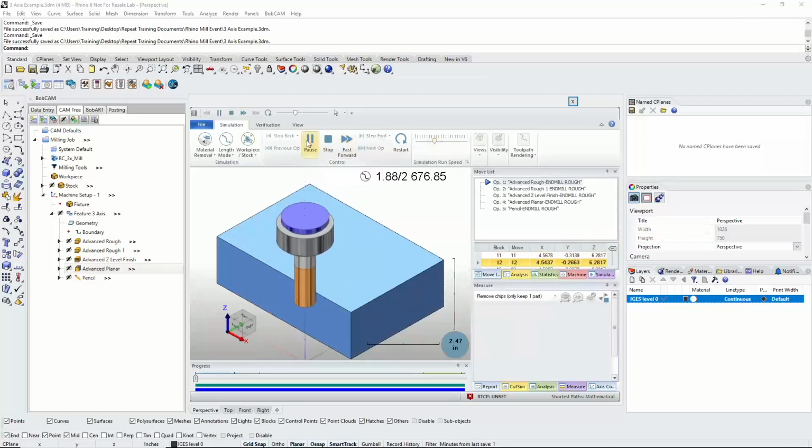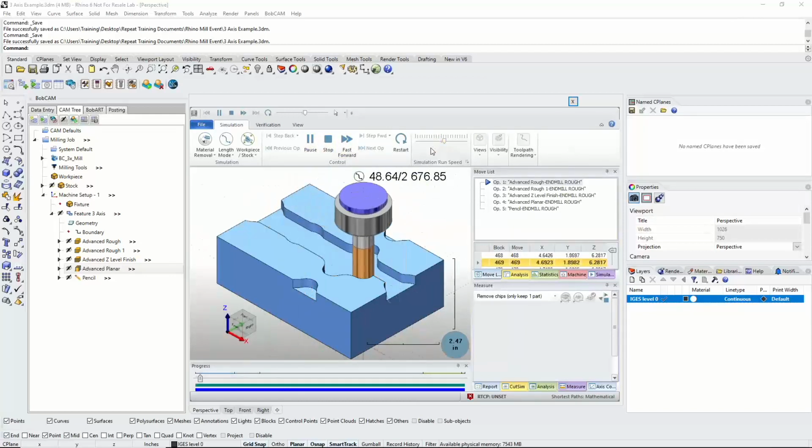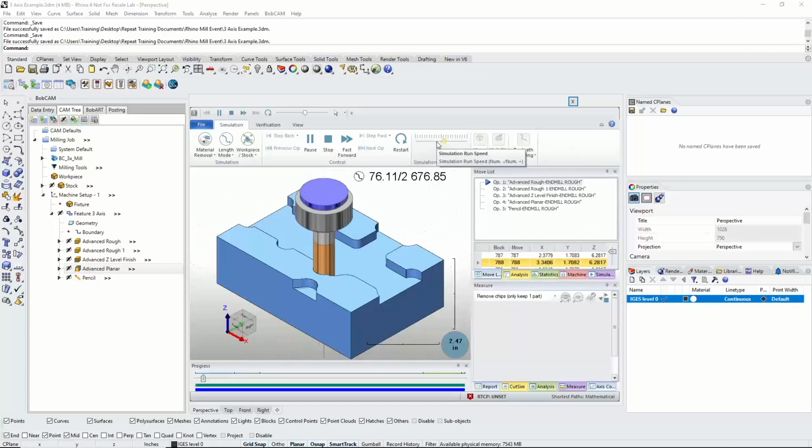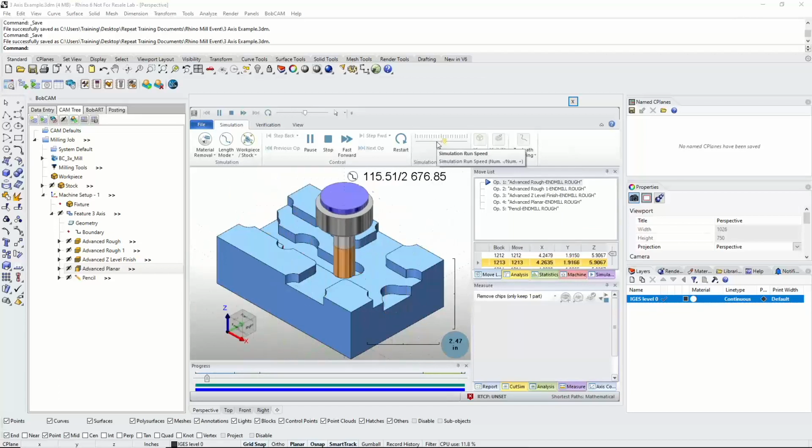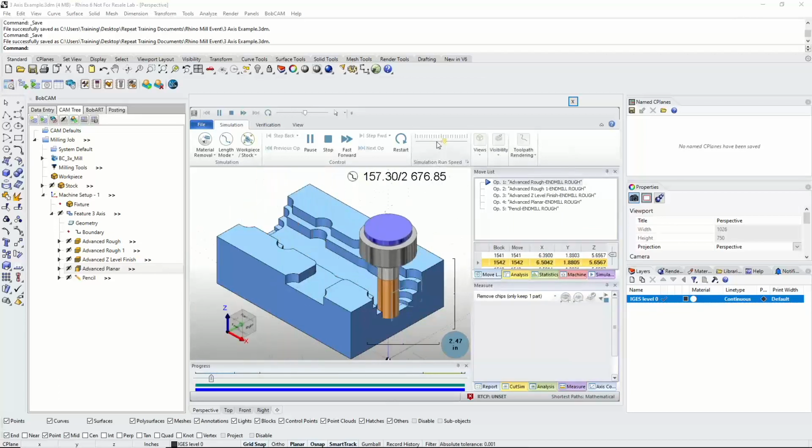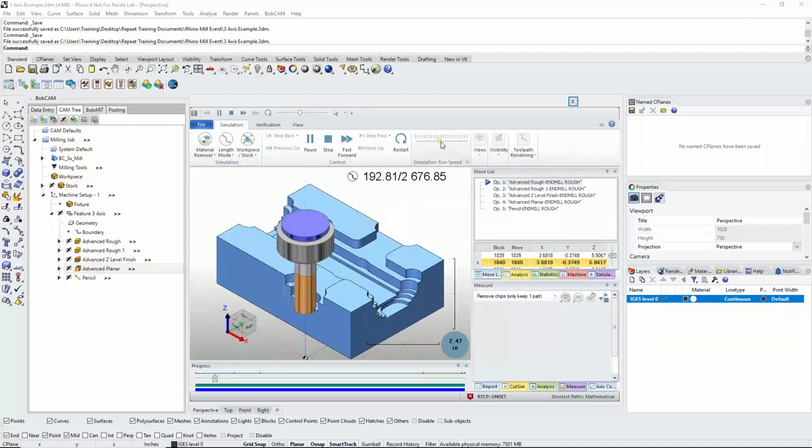And so this is the 3/4 inch tool going in, and it's just going to start cutting everything that it can. Now, I don't want to go too fast because I want to catch the intermediate steps that happen along this, but they shouldn't be happening until the end. So it's going to rough everything out. And then right here, we'll start to see them. So we got these big steps in the part. And this is going to go back and recut those steps as it works its way through. So something like that all the way around.